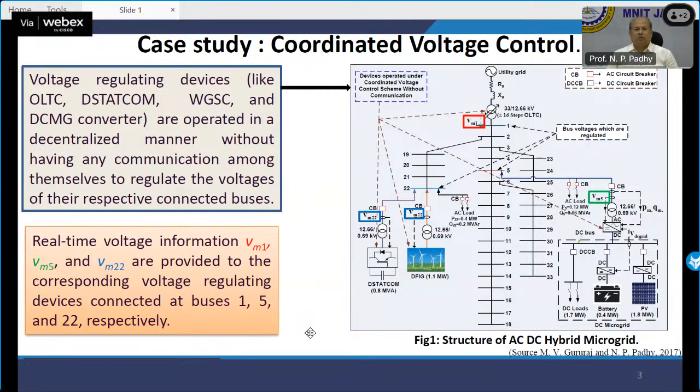Please remember. Have you seen a wind power plant? No, you must visit. If you see a wind power plant, you will find a substation just next to its base itself, and that is nothing but this transformer, which is of 0.69/11. But in this case, the system is actually IEEE, so we made it 0.69/12.66 kV. Is it okay?